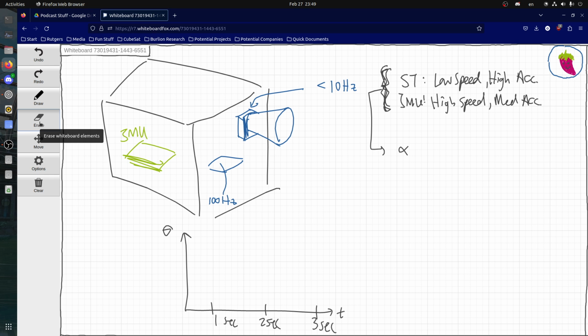What it comes down to in a Kalman filter is how well you can quantify the uncertainty. That's usually a very hard question. You're asking how we bound or measure this uncertainty, and then how we use that number to find the optimal value out of the data we're collecting. Blue Canyon does that very well, which is why they have a computer inside their ADCS.